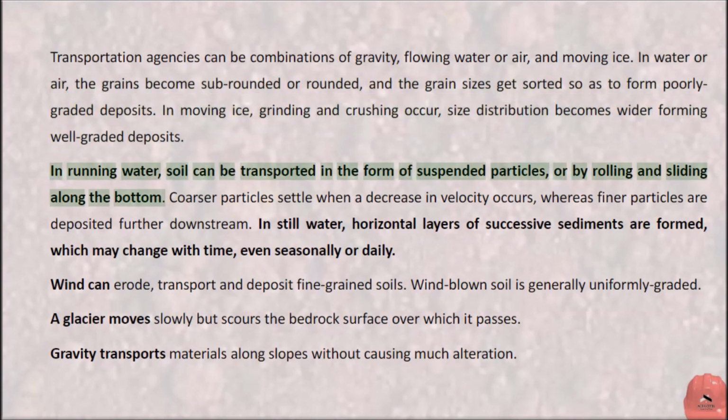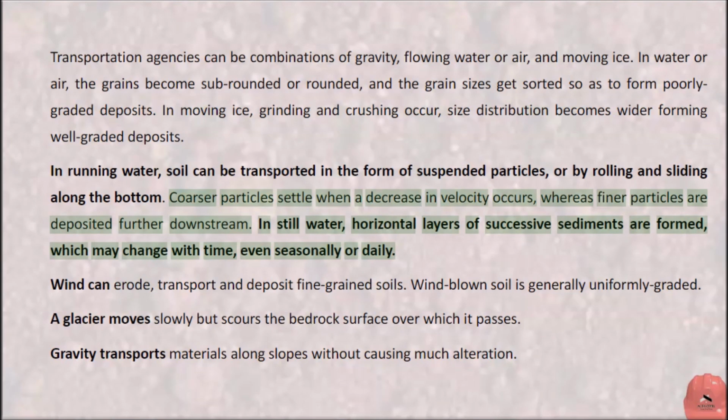In running water, soil can be transported in the form of suspended particles, or by rolling and sliding along the bottom. Coarser particles settle when a decrease in velocity occurs, whereas finer particles are deposited further downstream. In still water, horizontal layers of successive sediments are formed, which may change with time, even seasonally or daily.